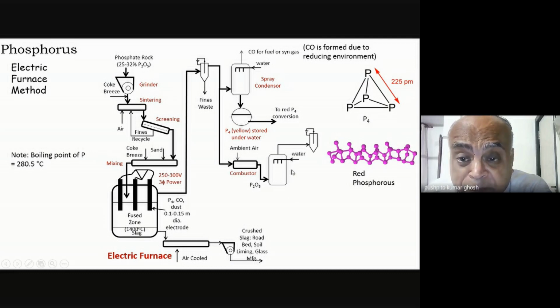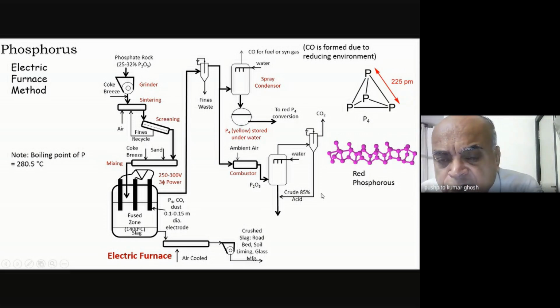And this P2O5, well, again, there might be some fines. So you have another electrostatic precipitator here and let go the carbon dioxide in a clear gas form. And what you can also do, because I'm working now with P2O5, is make extremely concentrated phosphoric acid, 85%. You remember we could barely touch 50 to 60% with the wet process. So obviously the cost of making concentrated acid from a dilute acid can be circumvented in this process.